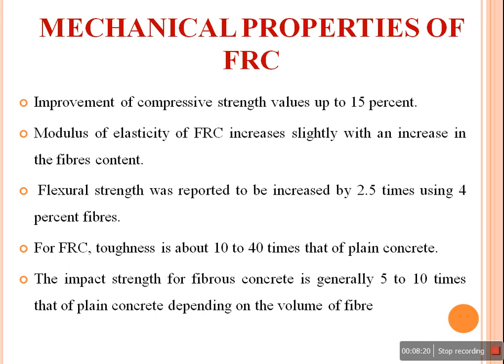So let us see the mechanical properties of fiber reinforced concrete. Fiber reinforced concrete has been studied by various researchers all over the world, and these are the conclusions from different researchers. Improvement of compressive strength values up to 15%. Modulus of elasticity increases slightly with increase in fiber content. Flexural strength was reported to be increased by 2.5 times using 4% fibers. For fiber reinforced concrete, toughness is about 10 to 40 times that of plain concrete. The impact strength for fibrous concrete is generally 5 to 10 times that of plain concrete, depending upon the volume of fiber.